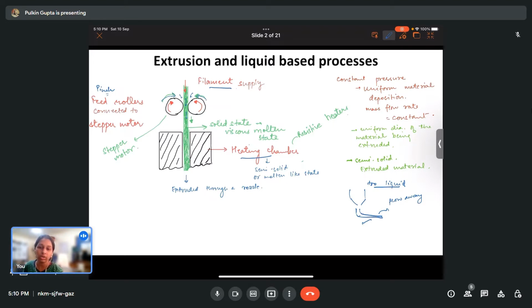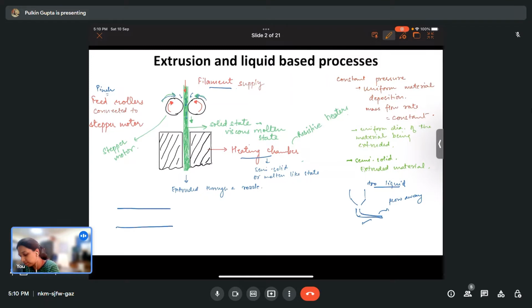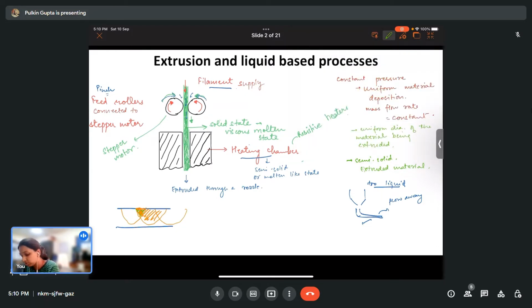Now, another important aspect is, as we had seen in the last lecture, that in SLM processes it is necessary to maintain overlapping of the layers. We saw that suppose this was your layer, and these were your track scans. It was necessary that whenever you print the second layer, a portion of the first layer also melts.